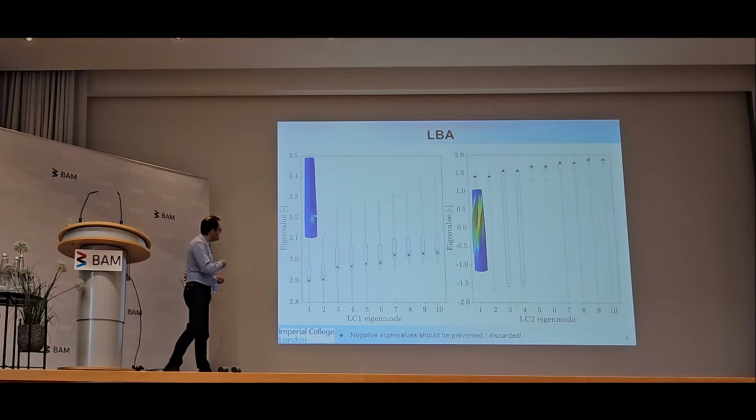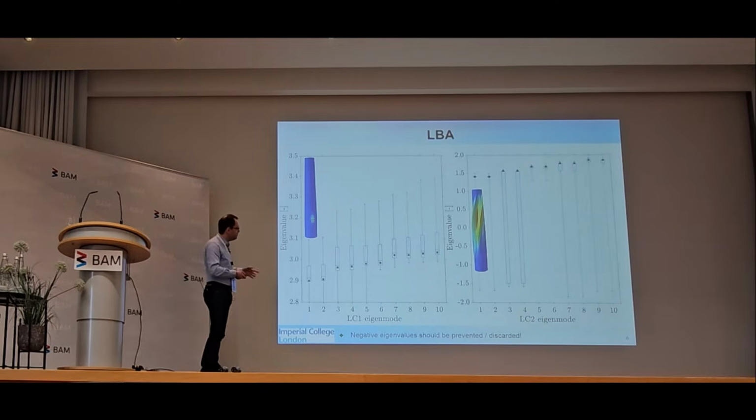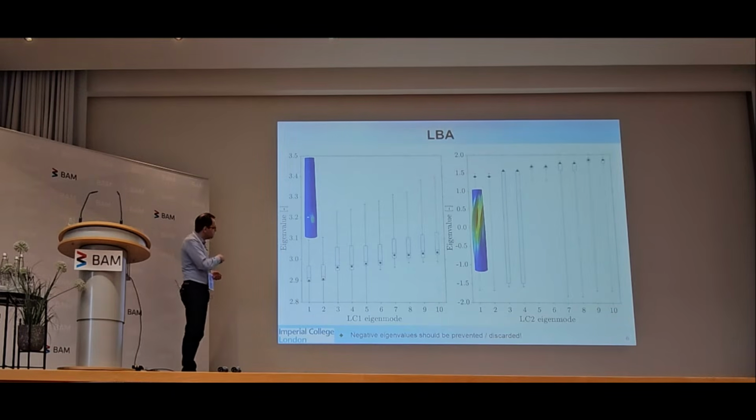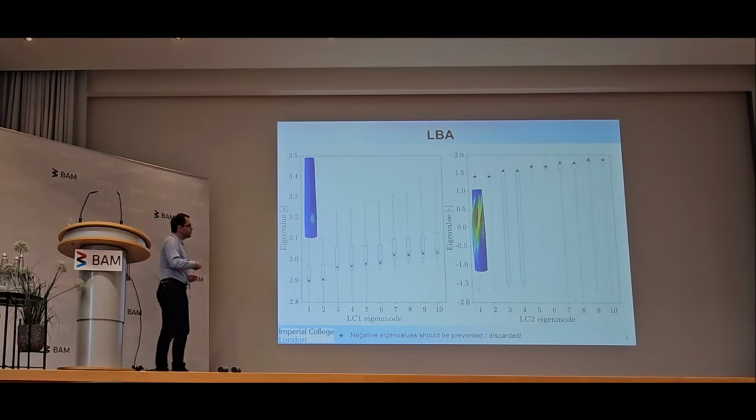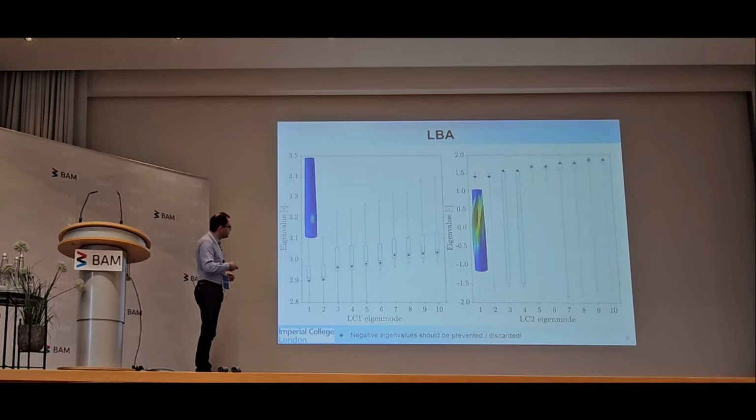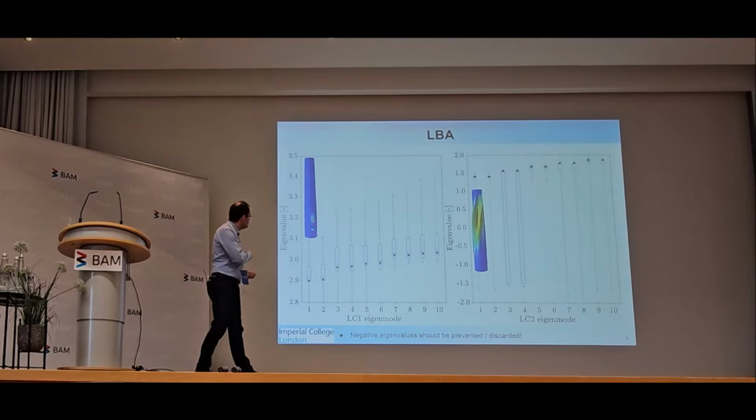Participants were also asked to submit a picture of the buckling mode, and everybody got this as the mode, so that was good. And there was a spread in results, and the spread is really attributable to meshing. Because the coarser your mesh is, and some meshes were unfortunately quite coarse, the stiffer your structure is. And the stiffer your structure is, that is, your shape is more constrained, you have to apply a higher load to achieve the same